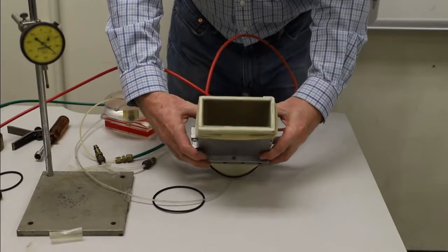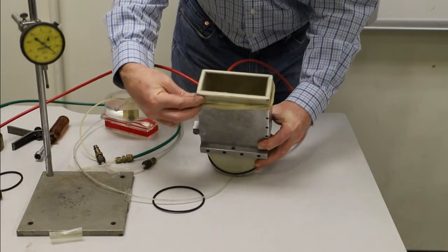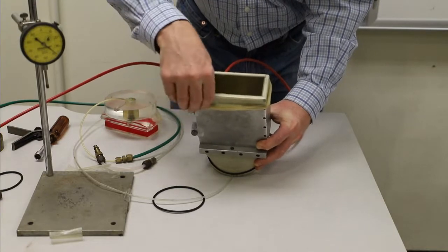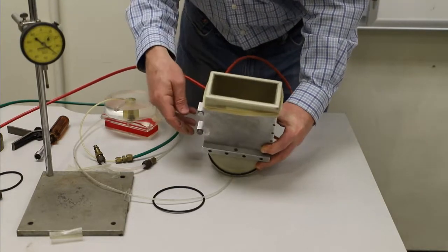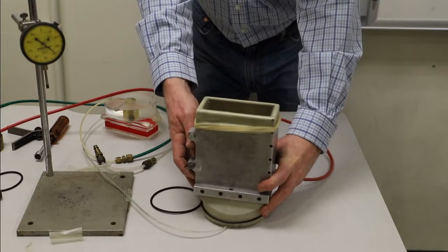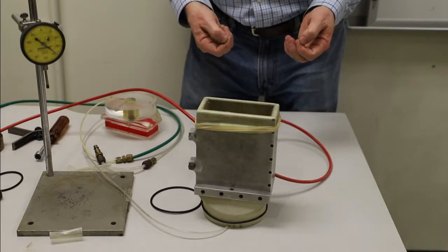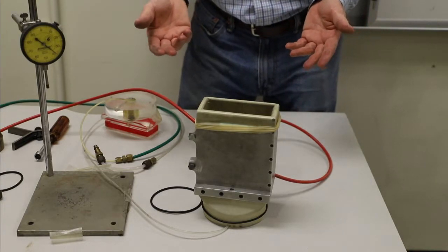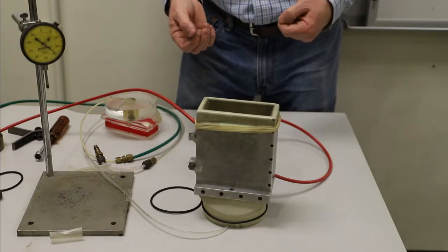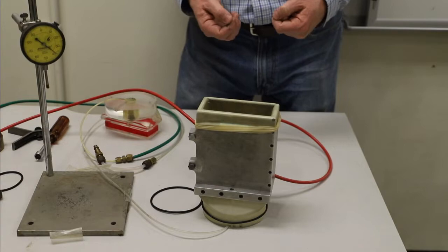So here we go. We have a mold with membrane in it. Again, I can hear a slight leakage, but as long as it's holding the membrane in place, that's okay with us. So, making a prismatic sample is one of the things we're doing differently. The other is we want to build a relatively high density sample in comparison to the triaxial one.